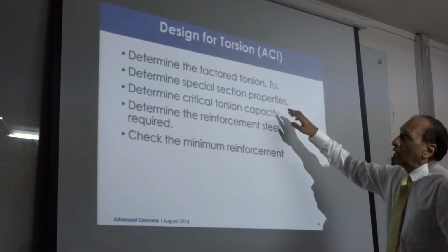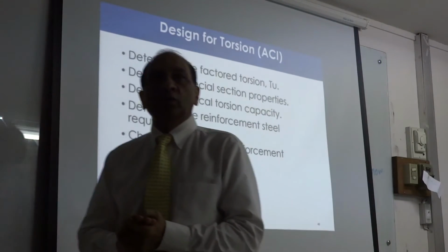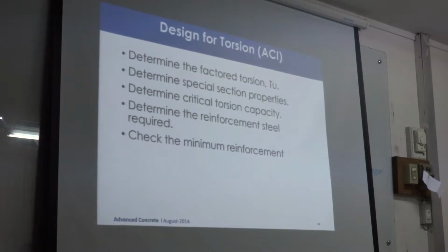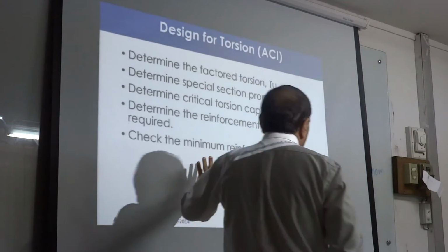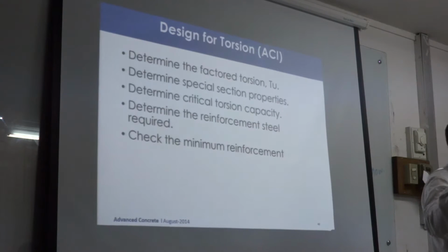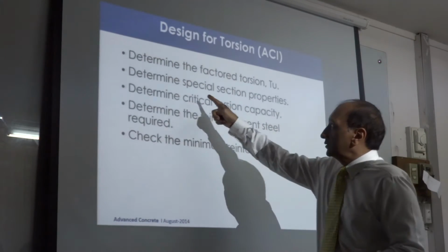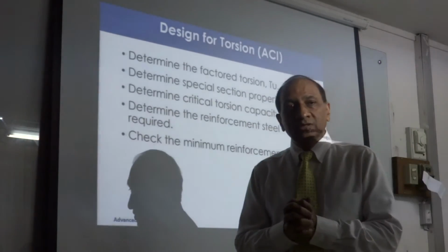Now within that, we come to torsion. When we want to combine torsion and shear, what do we do? We already decided that now we treat them independently first and simply add. This is so much simpler than what we used to learn, in which you need to calculate the available tension capacity of shear and torsion combined, because both of them are trying to eat into the same tension capacity of concrete, one side positive, one side negative. So the equations are really complicated, as you can imagine, right? Now torsion we can separate into independent problems.